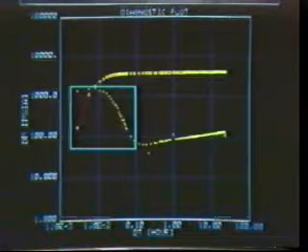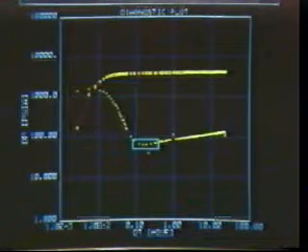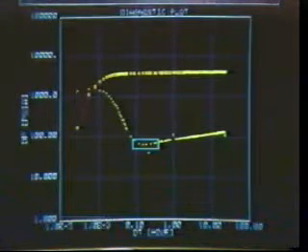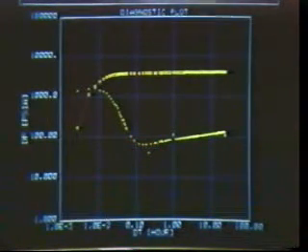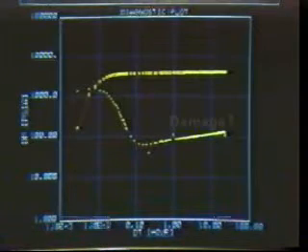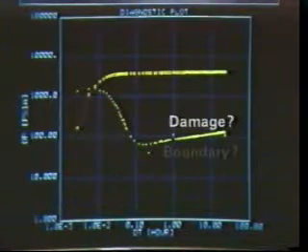Following the wellbore storage influence period, the derivative values appear to stabilize at an elapsed time of 0.1 through 0.35 hours, indicating the infinite acting radial flow period. The short duration of the radial flow period, followed by a steady increase in the derivative values throughout the rest of the test, suggest either severe wellbore damage or the presence of a near wellbore boundary.